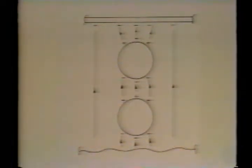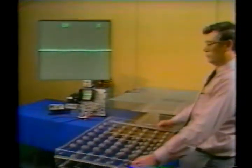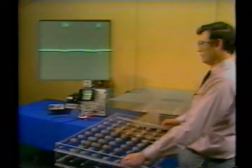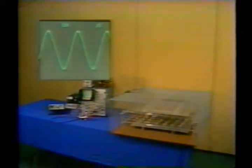Surface currents induced in a ground plane by an overhead conductor illustrate the method of images. Also illustrated is the superposition of fields due to line currents to satisfy boundary conditions. Here is a metal cylinder mounted over a metal ground plane. The cylinder is shorted to the ground plane at one end and driven by a current source at the other. This is familiar as an EQS situation where the same cylinder is insulated from the same ground plane and driven by a voltage source.